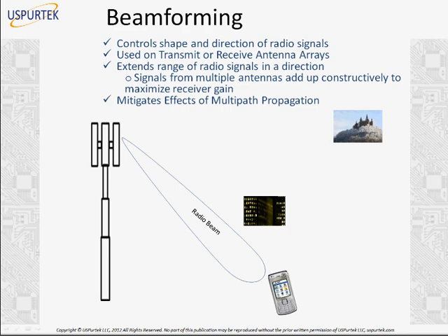So there's a question. So we can determine the best path the signal should take in order to reach a client device. Well, yes, that is true. So see, most preferred is always line of sight. But then line of sight may not work all the time. There could be obstacles on the way. So that is true. That based on the feedback received from the client device, we can adjust our signal strength, direction, and everything else. If we go in detail into the formats used in LTE and GSM and in other new Wi-Fi, new 4G wireless broadband standards, we'll see how that is done. But that is not covered in this webinar, the details of that. But definitely that is possible.